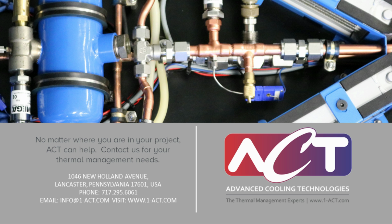So wick degradation plays a huge role. You need to be very sensitive of the amount of fluid charge that you're putting into the system. There are certain design aspect ratios that need to be taken into consideration. So there's a lot to be said there. We do have some standard tests that we recommend being run for those systems. And that, again, if you reach out to Dennis and his team, we can have some conversations about what environments you are expecting and what we would recommend to make sure you're getting a good product at the end of the day.